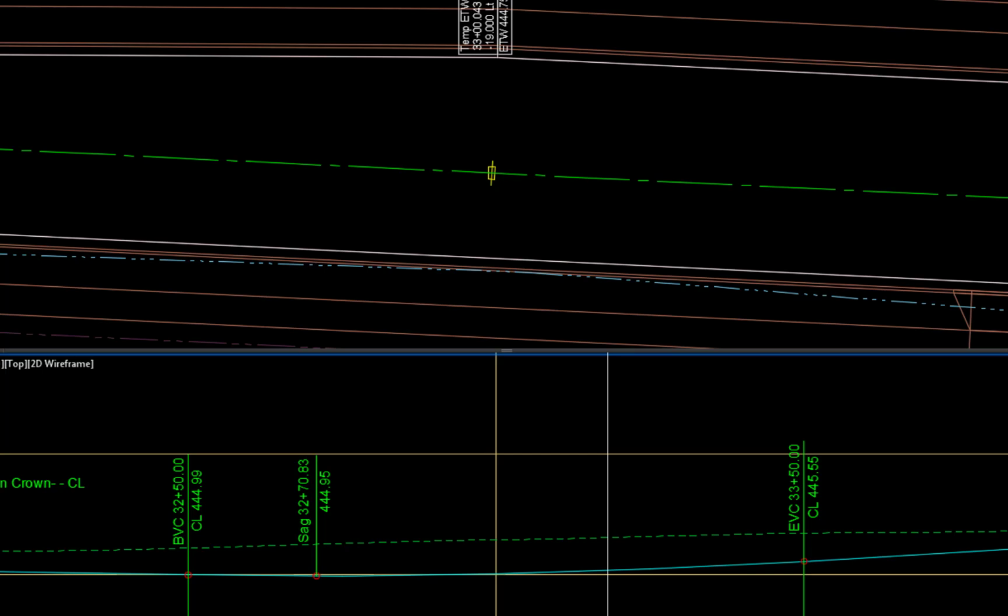If a variable width portion of the ETW alignment is within a vertical curve, the vertical curve needs to be modified. Such modification should be made prior to adjusting the ETW profile for an offset distance that is different than normal. The 100-foot vertical curve at 33+00 needs to be split into two vertical curves with the point of compound vertical curve of the two curves being at 33+00. New PVIs will be at stations 32+75 and 33+25.